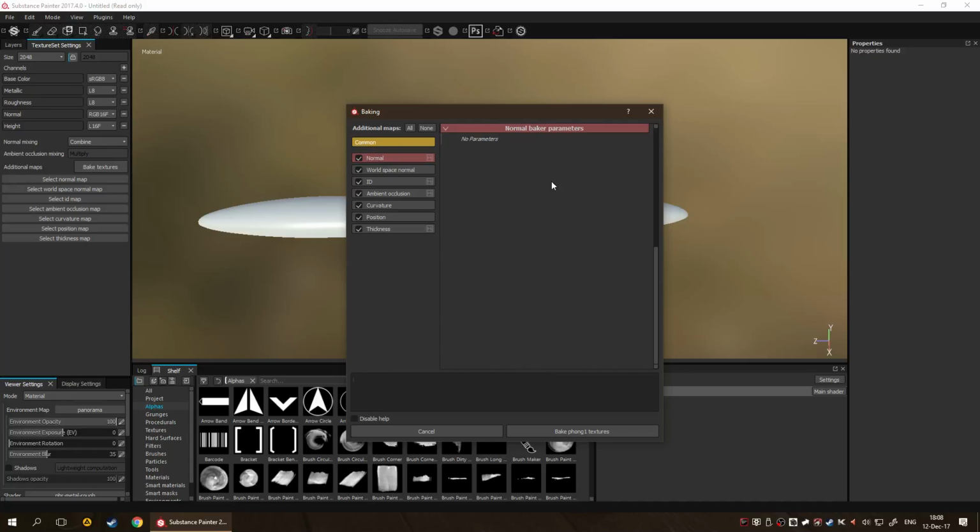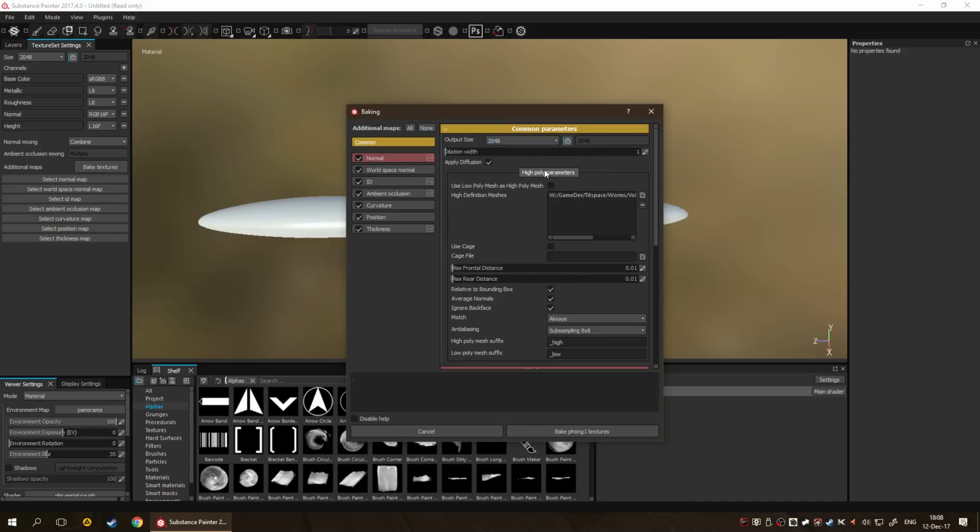Now we're going to go into normal map, which does not take any parameters, since it basically stems from the common parameters. Reason being is that the normal map is probably the most essential map that you'll be needing, since almost all of Substance Painter's results get merged and rasterized into a normal map. So whenever you have different things such as height or bumps or displacements, anything that involves changing the perception of a particular detail will most likely always be collapsed on top of the normal map, and it will be exported as such.